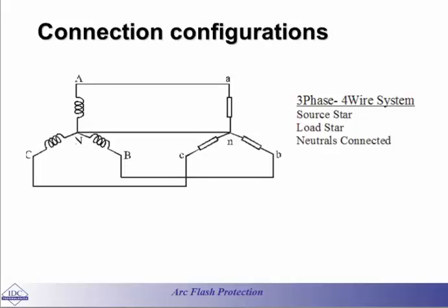All right, so the decision between AC and DC is first of all AC. And in AC, between three-phase AC and single-phase AC, it is three-phase AC. All right, so now that it is three-phase, we can have different connection configurations. That AC three-phase could be either star or delta. Of course, we have got zigzag, that I'm not going to talk about right now. So the star or Y connection has got a neutral point, but the delta does not have any neutral point.